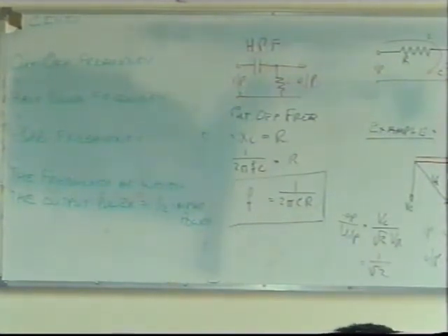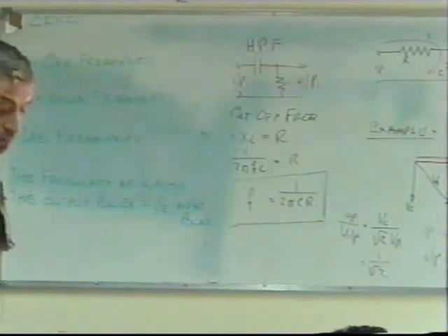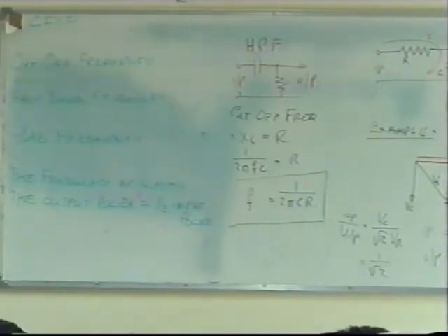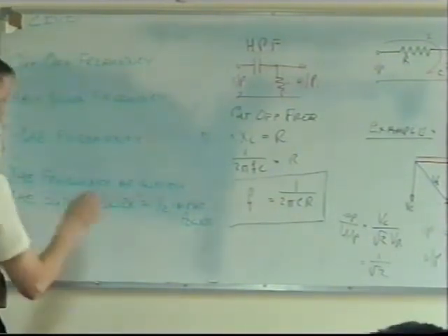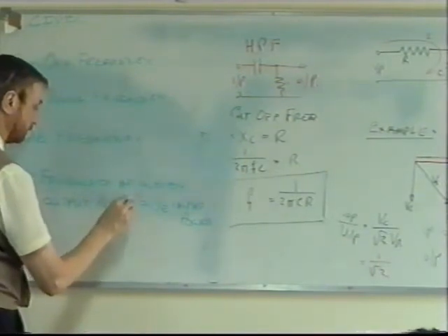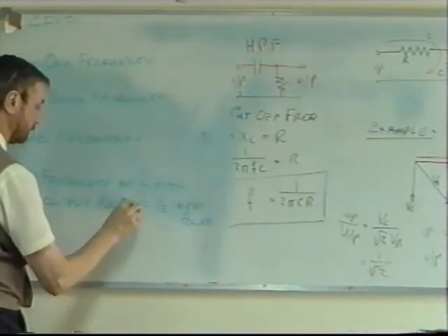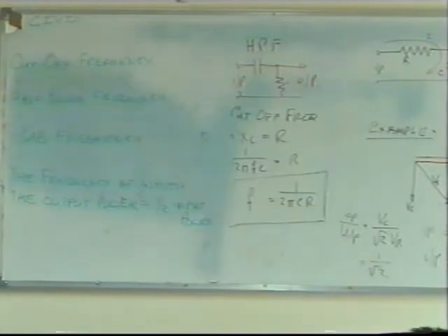And it doesn't matter what type of filter, and as we'll see later, even in tuned circuits we can talk about half-power frequencies. The frequency at which the output power equals half the input power. I'm talking about power, the power ratio. Yes, that's right.